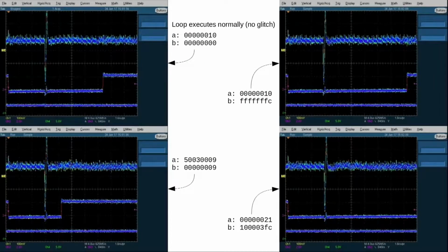And here we have screenshots showing the different results that we have when we glitch at this timing location versus the first one. So we've waited through a couple more rounds of the for loop. Now, something else that we can notice in these images, especially the top left image, is that you can see when the for loop executes, and we can see a little pattern there, and that pattern repeats exactly 16 times. So from the power analysis, we don't necessarily know what instructions execute, but it really is very clear that there's a for loop that's executing exactly 16 times.